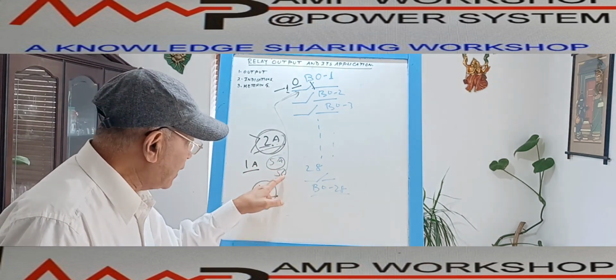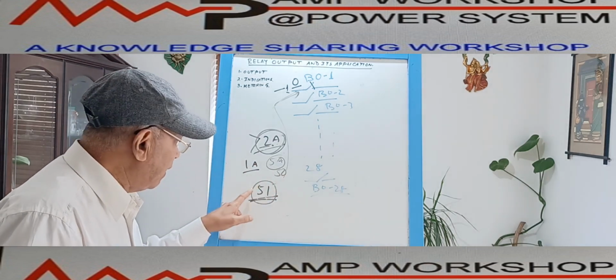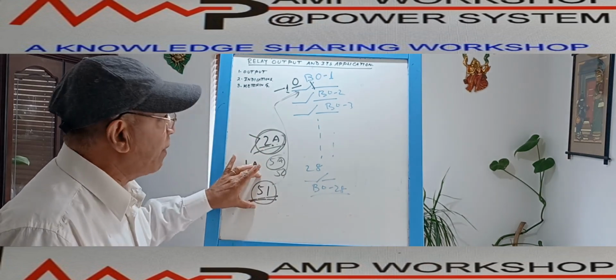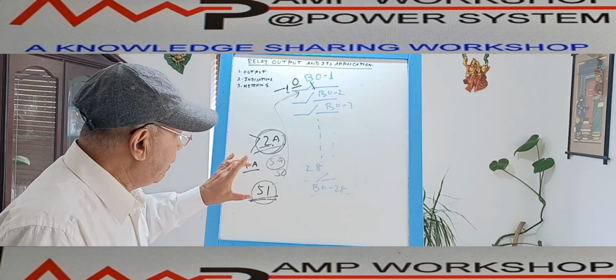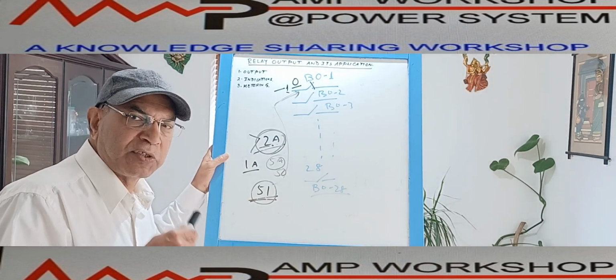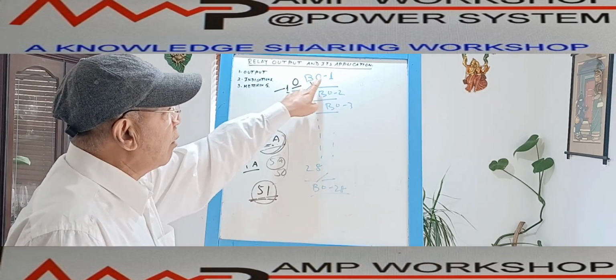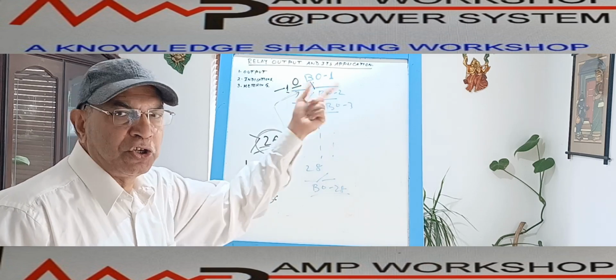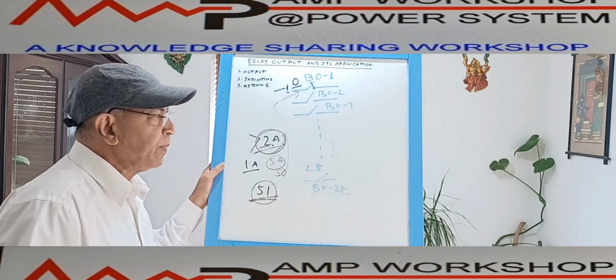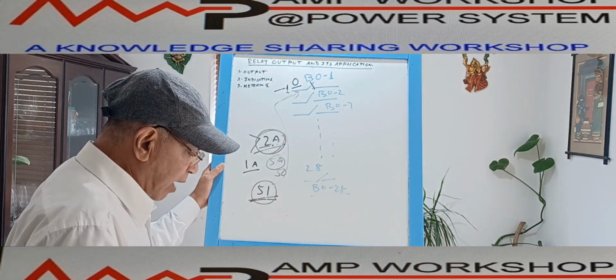That means when the instantaneous overcurrent as well as the IDMT overcurrent is operating, and the relay senses this operating overcurrent condition, the relay will immediately activate the main relay function. The relay CPU will give a command to the output contact BO1 to change over, and then output contact 1 will be activated. Now, how will I use this output contact?